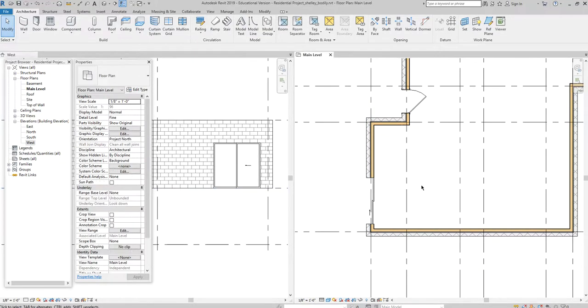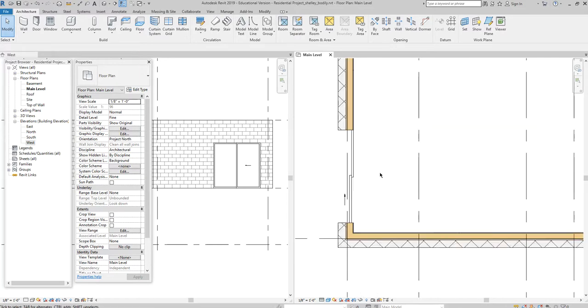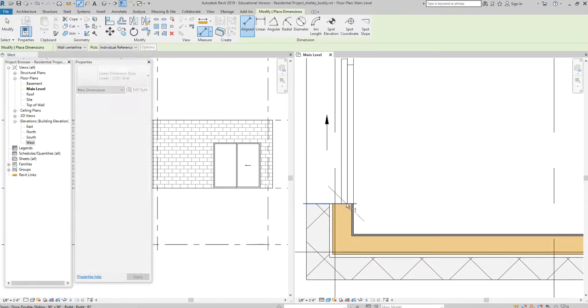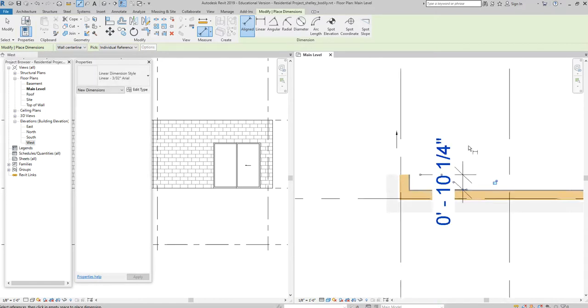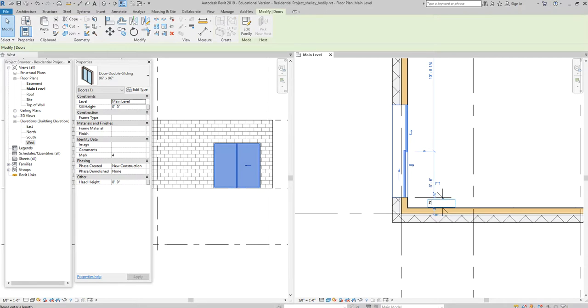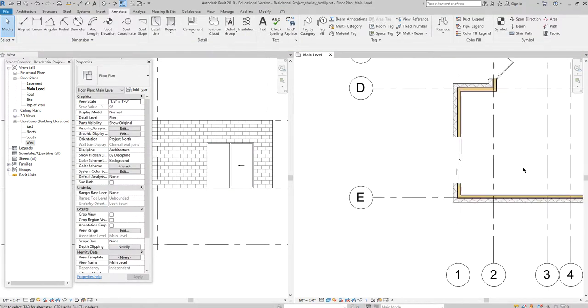Now I just need to position it wherever it ends up needing to be positioned. So I'm going to use my little dimension, annotate, aligned, click, tab, click. And maybe I want it to be 2 feet off of that wall, 2 foot, enter, click, delete. There we go.